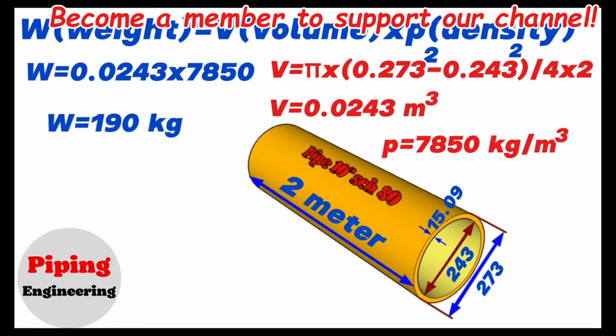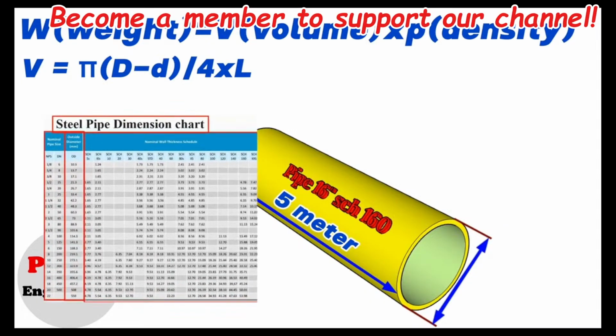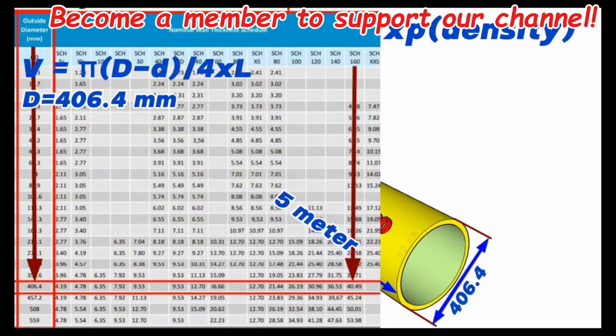Now let's calculate the weight of a 16-inch iron pipe with a schedule 160 wall thickness and a length of 5 meters. Since I know some of the calculations now, I won't repeat them and will move quickly. We will look at the row showing nominal pipe size 16 inch in the pipe size chart. From the chart, we find that the outside diameter of the 16-inch schedule 160 pipe is 406.4 millimeters and the wall thickness is 40.49 millimeters.